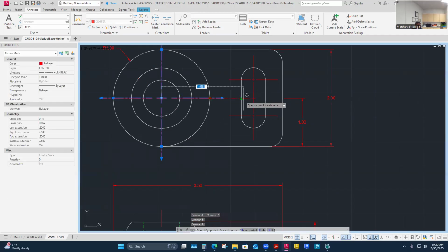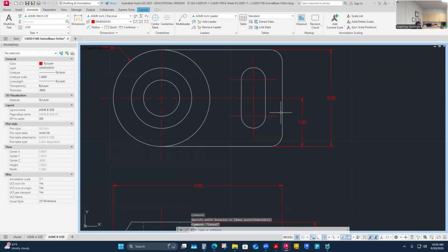I'm going to drag this center line out through there like that. That's part locating in a way. I've got this center line feature of a cone part, this through bore. Now I'm basing the front face to the center line off of a locating. So I'm establishing this as a datum. I'm establishing the part width off that datum. So this is good. I like this. It's a location.